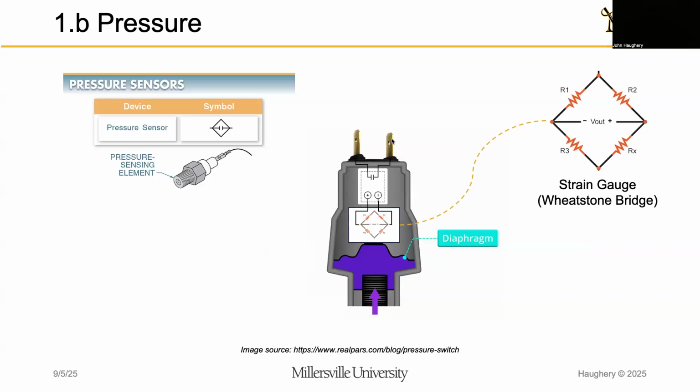So again, in a pressure transmitter that's solid state, we're using a strain gauge in conjunction with a solid state relay internally. And so there are no moving parts save the diaphragm. There's the liquid or fluid that's pressing up against it, but the circuitry has no moving parts. And that's the key distinction for this slide deck: solid state means no moving electrical parts.